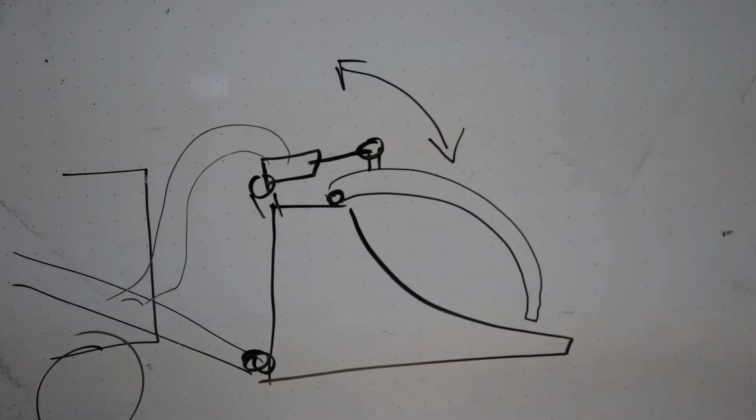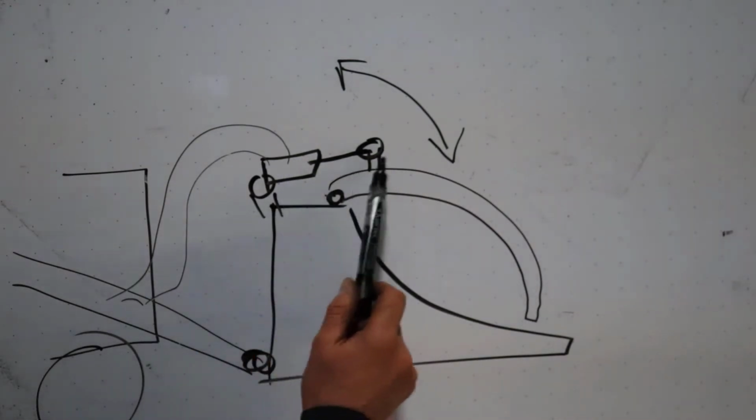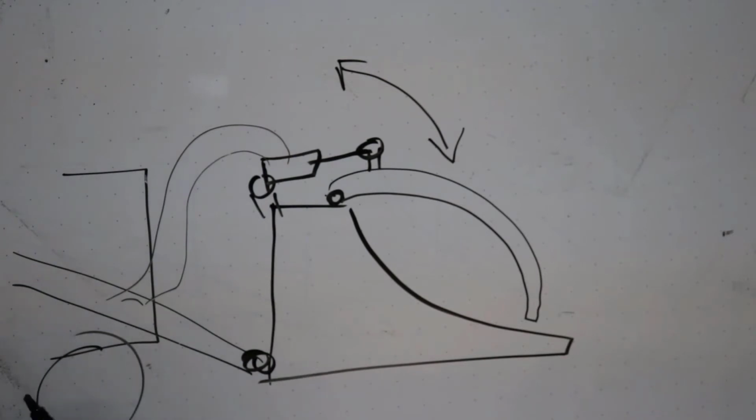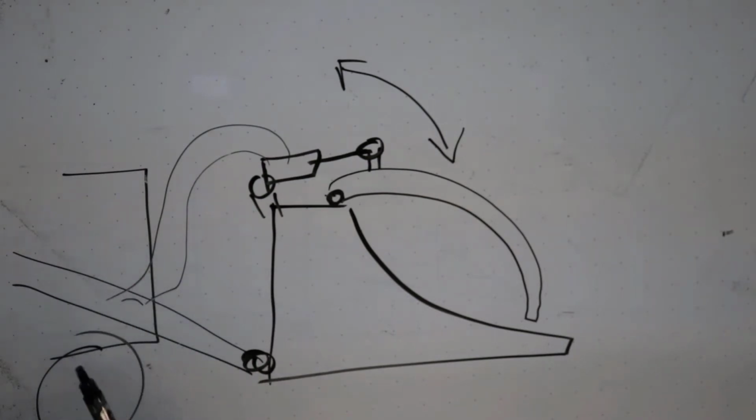Because I'm cheap, I'm not going to go to any of the manufacturers and buy myself a grapple kit. I am going to build it from scratch. So I'm going to go get a grapple or build one somewhere, like an auction sale, or just build one out of some steel I got lying around. I'm going to put a hydraulic cylinder on there because hydraulics are nice and handy compared to having cables or winches or some other mechanical means. And I'm going to tie the hydraulics into the backhoe's existing hydraulics.